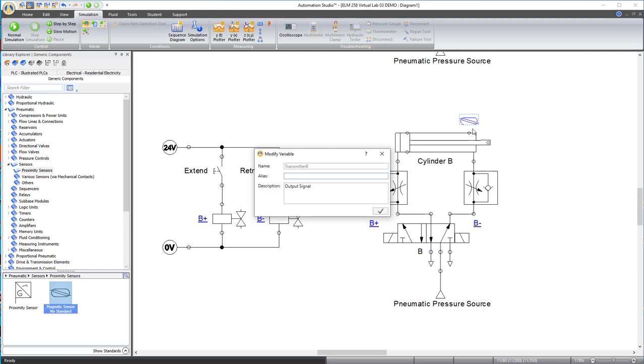And so what's going to happen is when the rod extends, this little diamond-shaped dot that's on the piston is going to slide up and make contact with that. And that's going to simulate the way the real cylinder has a magnet in here that comes up, and the magnetic field causes the magnetic sensor to trip. So, all right, the alias for this, we're going to stay consistent with the HAS200 notation. So it's cylinder B. So we're going to call this sensor B, lowercase b, 1.